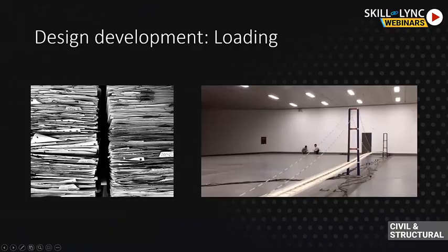So how do you get through the loading? Unfortunately, most of it is through codes, through design requirements that are drafted for each type of structure, generally in each country. Sometimes the codes are determined by the contractor. So, for example, I work on a bridge in India where the contractor is Japanese, and they impose that we use Japanese standards, even though we're in India. So it's really, the design codes are important.